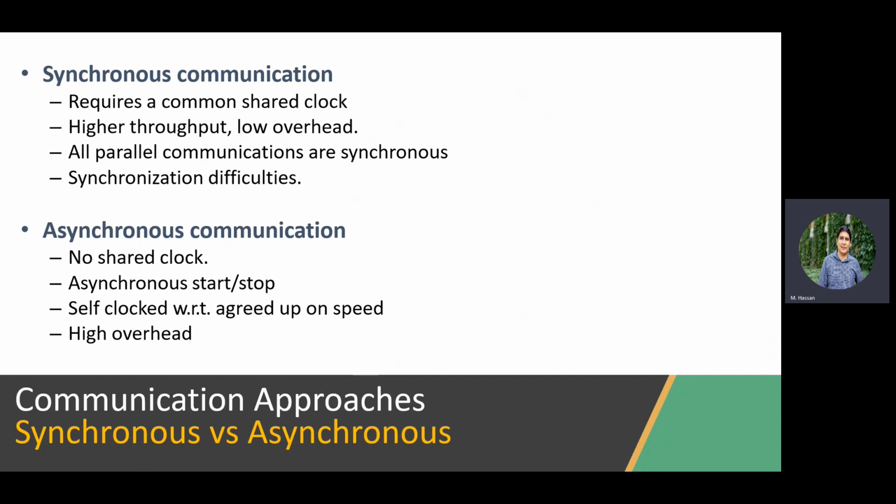So if I'm sending you something, for example, I send you a command, and after X cycles, let's say 10 cycles, I'm expecting the data. You don't need to tell me when the data is ready. Well, I am ready. Are you ready? Yes, I'm ready. So the three-way handshaking is not needed there, right? So synchronous communication is in fact much easier to handle from the protocol perspective.